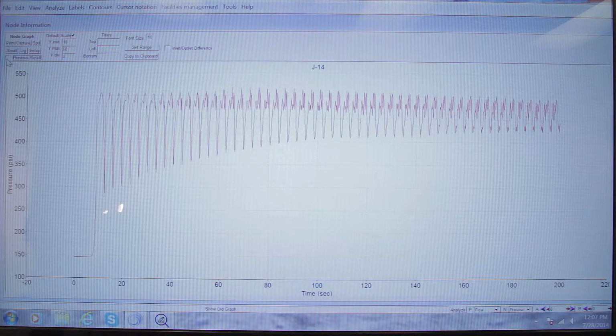So we're operating at 150 psi at this point, and when we shut that valve, we hit 500 psi, and my piping is rated to 285 psi. So this is a huge problem, and again, who knows what's happening on the side of the injection point, but this is the shock wave that he created, or she, sorry, in closing that valve. So how do you deal with this shock wave? This, again, is unacceptable. We have flexible piping, and we've overpressurized our piping system.